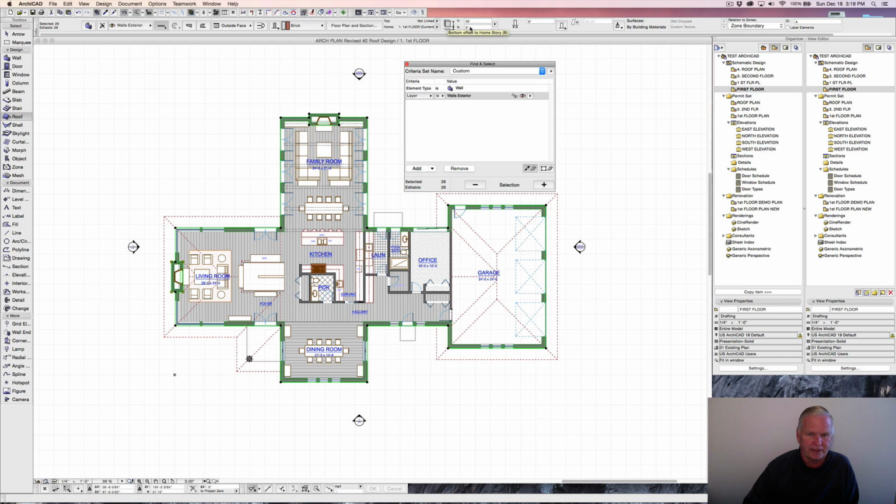And in order to calculate that, I'm going to make the assumption I'm going to use 12-inch TGI joists, or I-joists. I'm going to have 3/4 inch floor sheathing, so that's 12 3/4. And I'm going to have 1.5 inch plate, so that is 1 foot, 2 3/4 total. Okay, follow me on that? So click on that area, and we're going to go minus, because we got to go below 0, minus 1-2.25. All right, so minus 1, 2 1/4, and that's changed all those exterior walls.